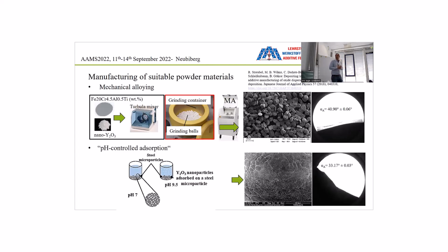We at our institute also thought about another process to get a powder composite, which is a bit more advanced, you might say, and we call it pH-controlled adsorption. So what we basically do is we throw our powders into water. Everyone will say, how can you dare throw this into water? Okay, in this case, we have stainless steel, so it's very well protected. So there are no reactions with the water.